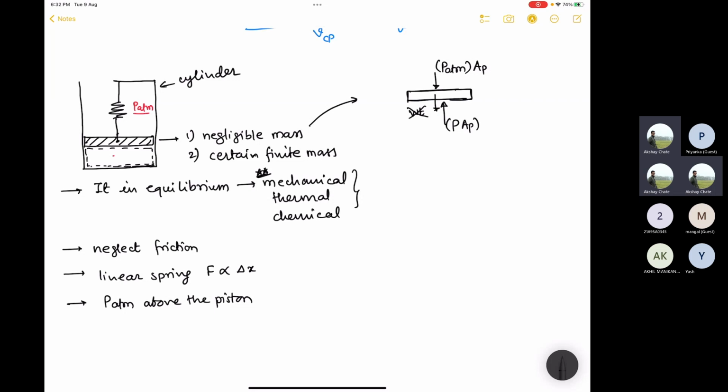And one more thing, let's say this is the simplest form of diagram that we can see. So if this is your system which is having negligible piston mass and no spring attached to it, in that case whatever the pressure that atmosphere exerts, the gas or the mixture inside the piston will also be at the same pressure. Now that is not actually a commonly seen case, so we'll draw the free body diagram of a typical case that we usually encounter. Here we'll have two components.